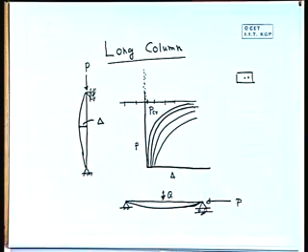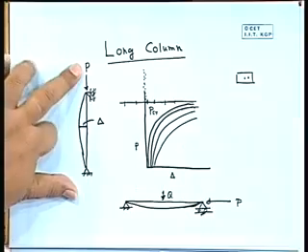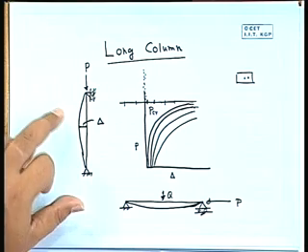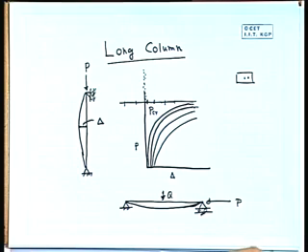Under a compressive force, we will assume everything is perfect, meaning the cross section throughout is uniform, and the material property everywhere is the same. There is no distortion or deformation within the member. So it is absolutely perfect. The load is acting at the centroid of the cross section of the member. The supports are absolutely perfect, properly placed at the two ends. So the whole thing is in a perfect condition. We want to get the load P at which we will get the critical load.